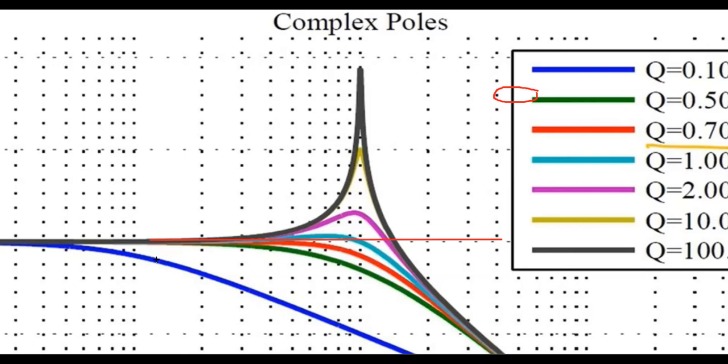And if I put the straight line mostly like this, you'll see the corner frequency maybe. It is very close to the blue line, but if I say this is the corner frequency, the cutoff frequency, the red is the best one. That means it will take everything in the left side and start to block in the right side. Yes, blue is very close to that one.